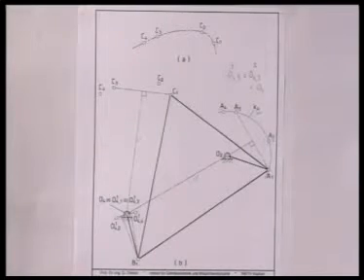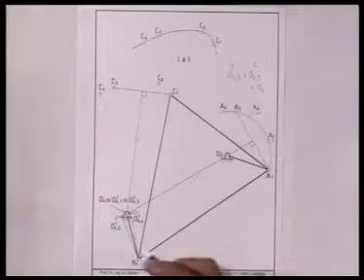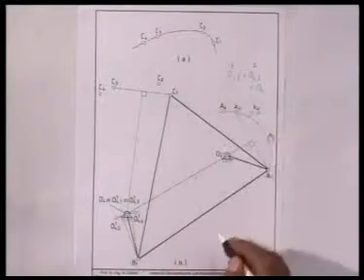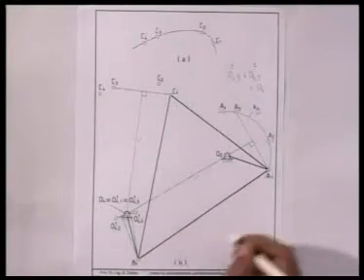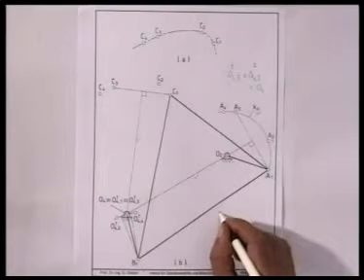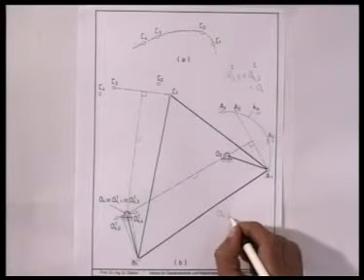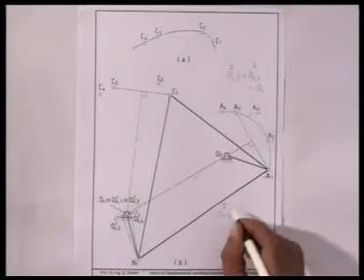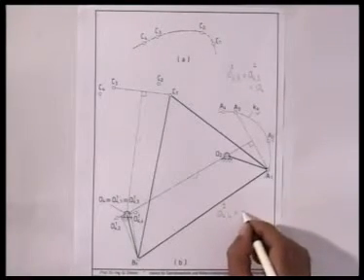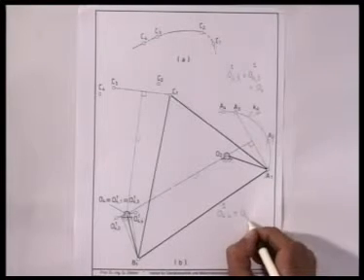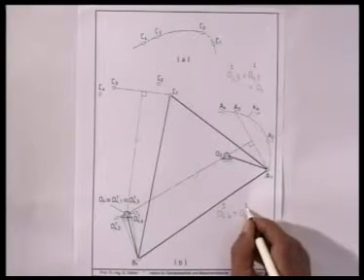As I said before, with reference to function generation problem, I could have chosen different inverted positions of O4 to coincide. I could have inverted the whole thing such that O4 for the 4th position inverted on the first position coincides with O4, 1, 1.